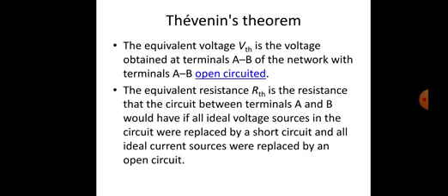It means the theorem applies to AC in exactly the same way as DC, except that resistances are generalized to impedances. Thevenin's theorem and its dual, Norton's theorem, are widely used to make circuit analysis simpler and to study a circuit's initial condition and steady state response.